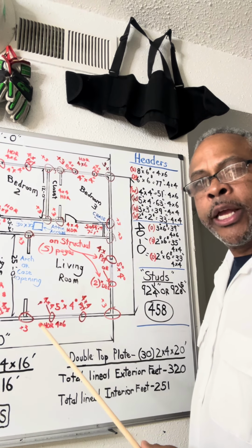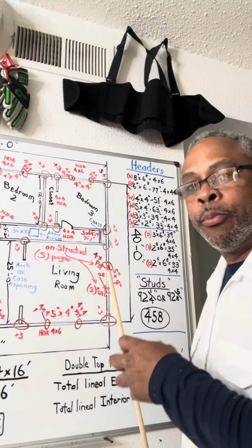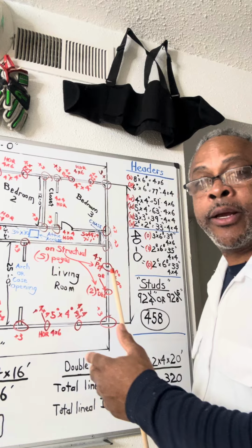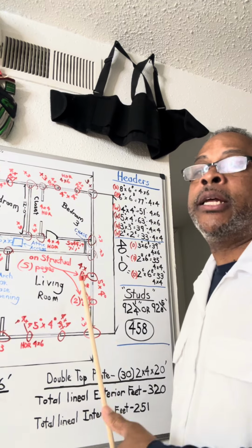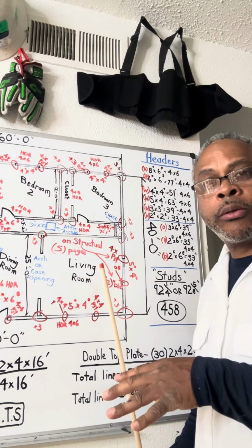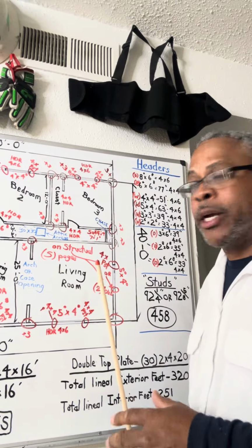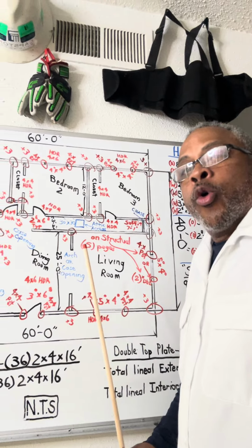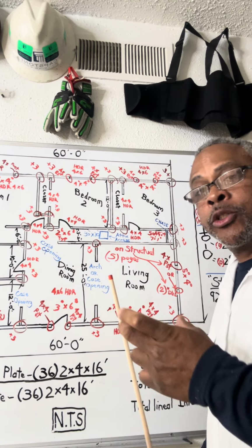And your bolts, your anchorage has to be specified. So you need that to also be at the right location. Because before all this framing goes on, you're going to have anchor bolts, hold down bolts sticking up out of the concrete. Your bottom plate has to be drilled at the precise area where those bolts are coming up. Because when you frame that wall and you lift that wall up, the hole goes over the bolt, the wall sits down, the man comes behind, he puts a square washer.